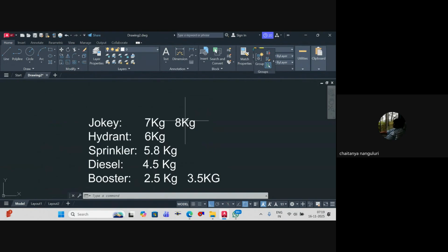Am I clear? Okay, then if your hydrant system is working, it's fine. Let's say more sprinklers broke. Then the pressure gauge is there at the sprinkler piping, right? So it will measure only the sprinkler system. So then the sprinkler pump will also start. Understood?